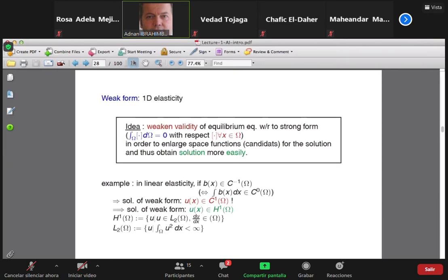So basically, this is the basis of any finite element solution software. So what does that mean practically? It means in this finite element computation, the only solution which is exact, even if you use the simplest model like the trusses and bars with two nodes, should be the reaction of the supports. In other words, you can say that the total external loading on the structure is completely and exactly matched by the reaction, but nothing else really, just that part there.